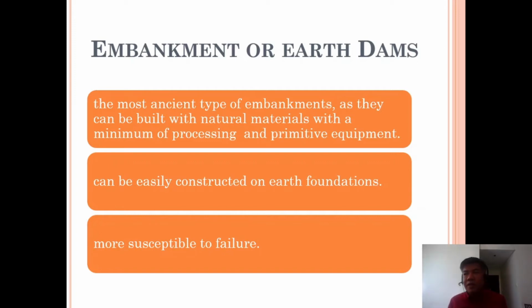Unlike concrete, which will not have seepage through its body, what they analyze there is the seepage below the structure, and they design other measures, like adding sheet piles, to minimize the pressure of seepage. So those are what we call earth dams.